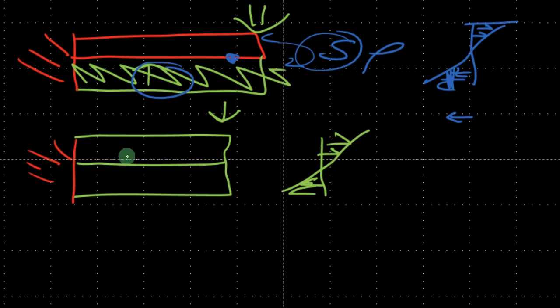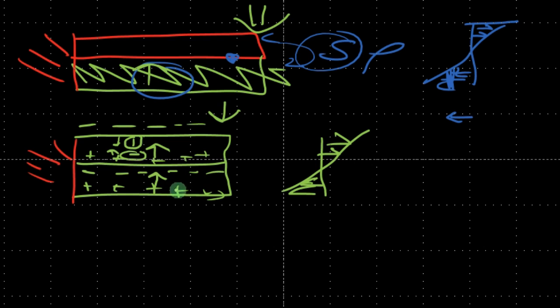So tension here. If we have a polarization vector going up, tension, we'll do what? Now we have to imagine the positive charge and the negative charge. Basically when you pull on it, they're going to come closer together. So this side becomes negative and this side becomes positive. So if we had both of these oriented positive, this would end up being negative because of compressive stress, and this will end up being positive. So these charges would actually cancel out.